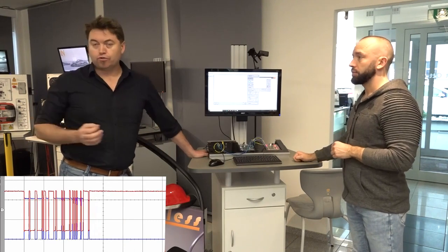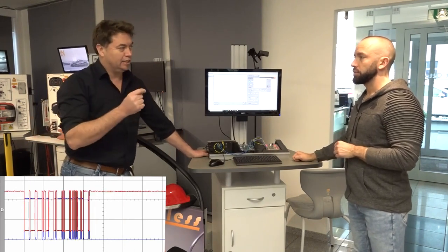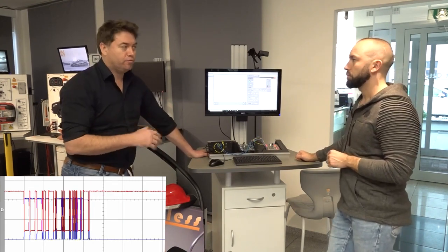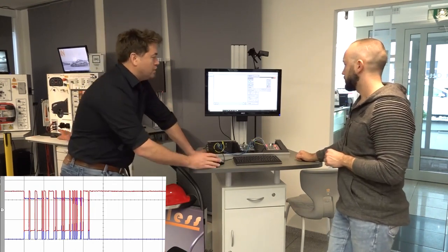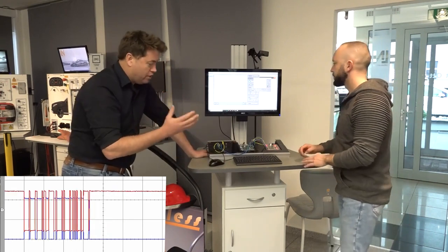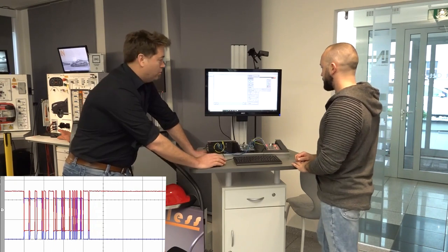If we go to high speed, which we said before is often used in safety critical systems or the engine control where things have to happen instantly, we're using high speed and it doesn't have this function. So if one of the wires is broken, the system will actually shut down and warn the driver or shut the vehicle down, according to what the problem is.